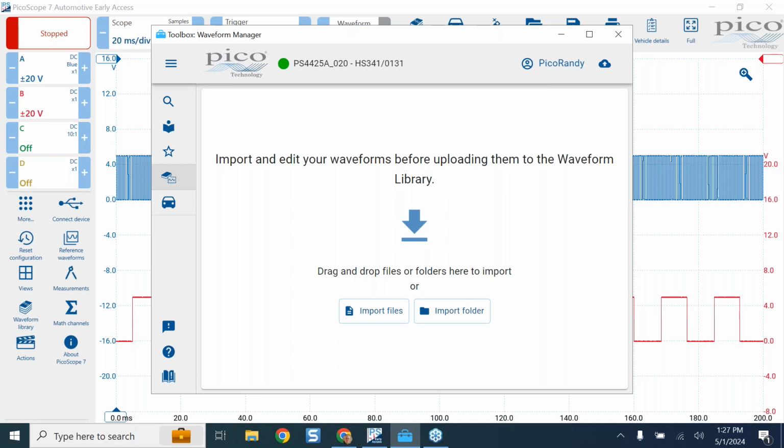It does depend sometimes on the update rate as well, but there are limits for that. So just as an FYI, if you're going to do a bunch, make sure that the actual waveform itself isn't too large. So maybe don't save the entire buffer. Just save what's pertinent, and then all of those will be checked and give you progress bars. And if one of them doesn't load or it gets rejected, it'll have a red X next to it.